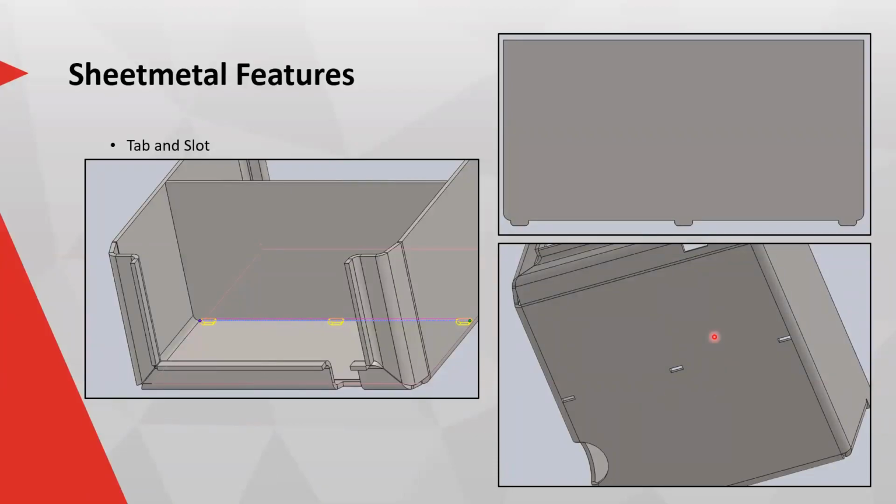And the second selection was this bottom face. And you'll see on my two separate components, what it does is it creates a tab and it creates a slot feature. It's quite useful that you can do it from a multi-body part environment, or you could also do it in an assembly environment where instead of doing multi-body parts, you're in an assembly and it's separate parts.